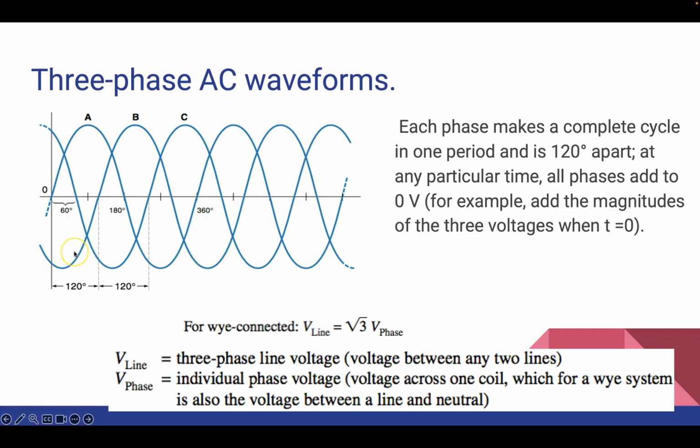In Y connected three-phase power, which is commonly used for distribution within facilities, the presence of the neutral wire allows single-phase loads to be connected or disconnected as needed. However, the delta connection system doesn't have a neutral wire, and the balance is inherently maintained in that type of connection.